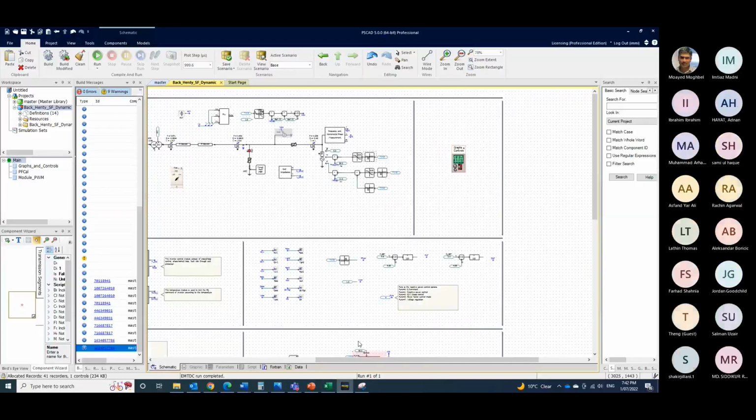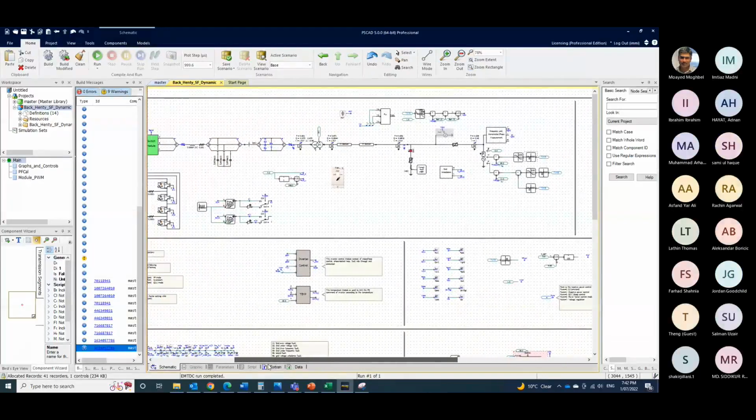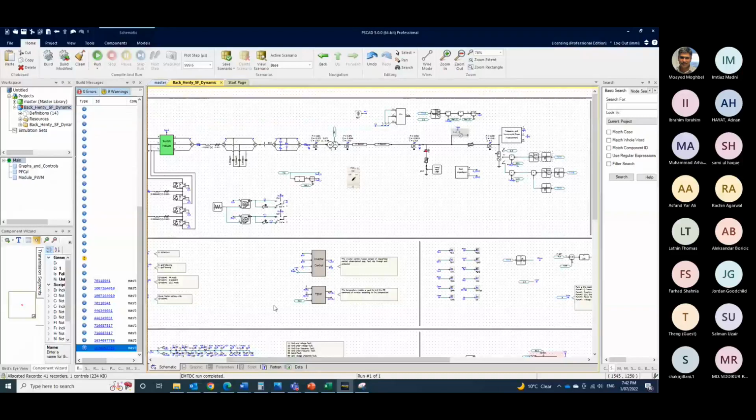One question, Dr. Imtiaz. How did you do the initialization in your simulation? Initialize, we just do this run. So you can run your model. In PowerFactory, at least, we know that the initial value comes from load flow, but PSCAD doesn't have load flow, so we need to give some initialization, which I believe maybe is not considered here.